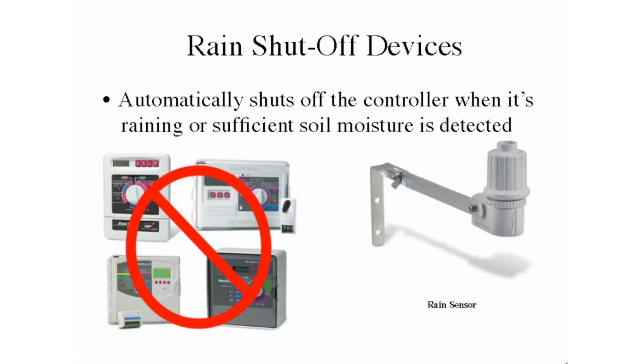These are the less effective, the idea of a rain shutoff device. Now, your irrigation should not be running when it's raining. For the price of dinner out, you can get yourself a wired or wireless rain sensor and add that to your system. Usually the rain sensors from any manufacturer work with any manufacturer's controller. So that's easy. You don't have to be specific to yours, so you can buy one. But I would definitely recommend, as a minimum, you get a device like that.